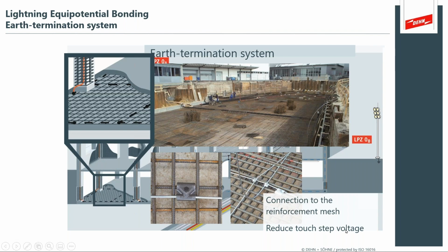You want low resistivity through the conductors into the floor, into the earthing system, so that you produce less voltage. You're trying to reduce touch step voltage. You're trying to create 0 volts. 0 volts means zero current between the parts. Bird on a wire. Everybody rises, everybody falls with a lightning event. So if there is some sort of catastrophic nearby wrath of God strike, you actually don't feel it because the voltage from any given surface is reduced.